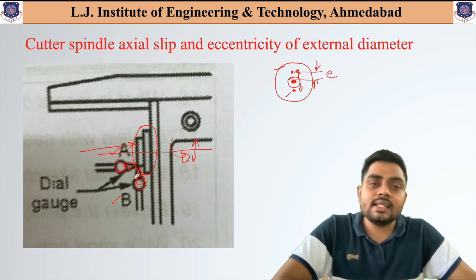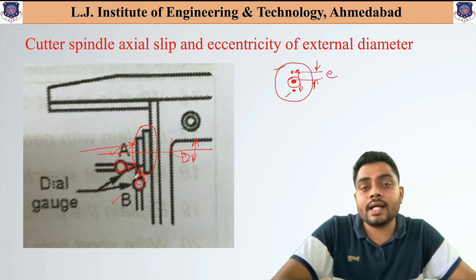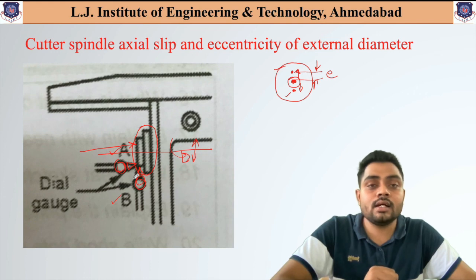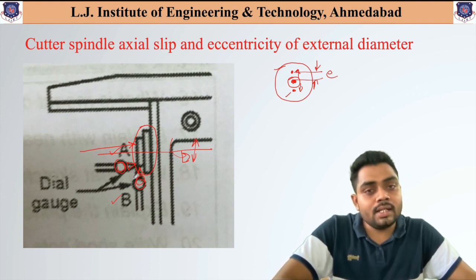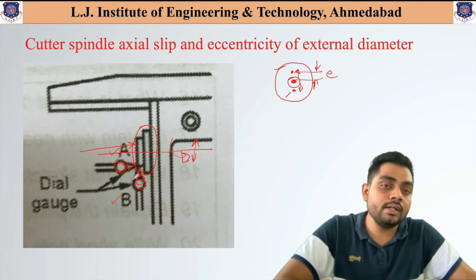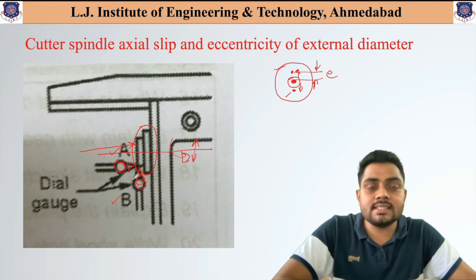These are the basic alignment tests required to check if the components or the parts available in the milling machine are performing with their exact required purpose or not. This alignment test is required at certain intervals, and it is the most and foremost important part. In most of the cases, the alignment test is carried out using the dial gauge indicator.